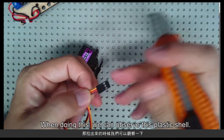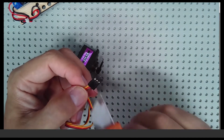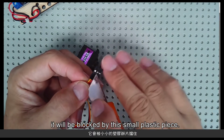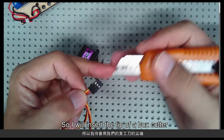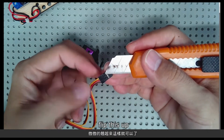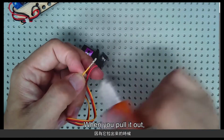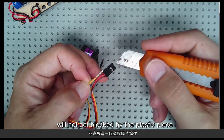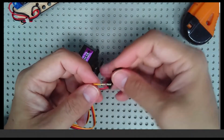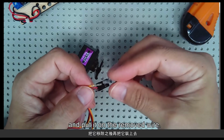When doing this, we can observe this plastic shell. See the part where the plastic contacts the metal. When the metal is pulled back, it will be blocked by this small plastic piece. So I will insert the tip of the box cutter into the gap and slightly flip this up, and then gently pull out the signal wire. When you pull it out, this copper piece will not get blocked by the plastic piece, so it can be removed easily. We can find another DuPont-lined plastic shell and put it on the removed wire.